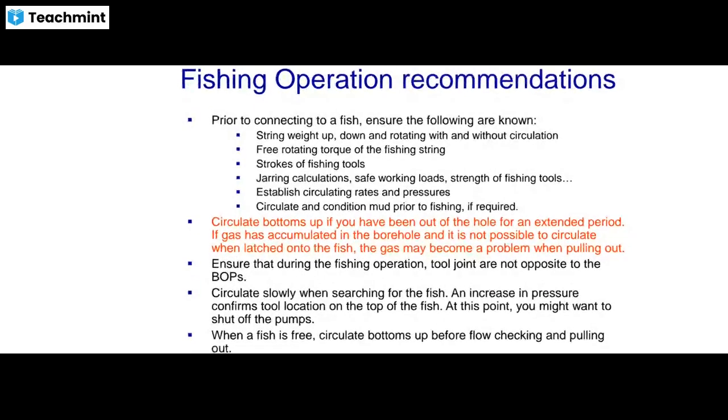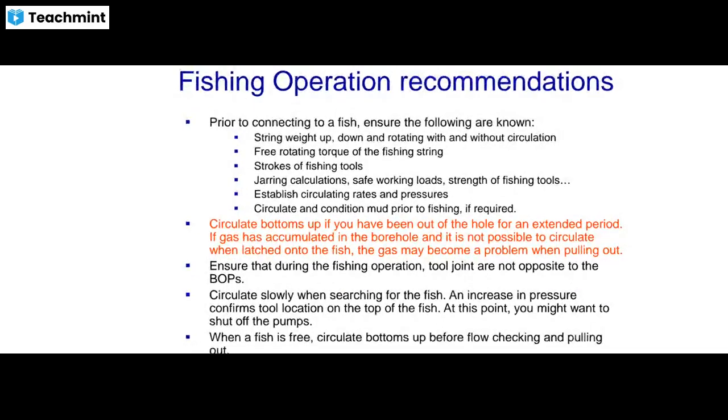Then fishing operation recommendations. Prior to connecting to the fish, we have to ensure the following are known: string weight up, down and rotating, with and without circulation; free rotation torque of the fishing string; strokes of fishing